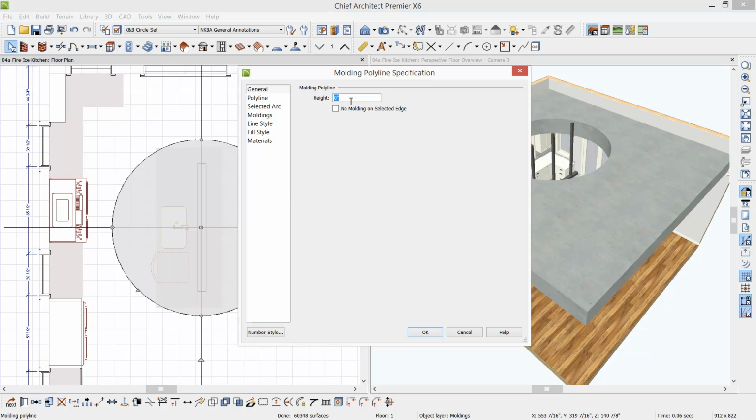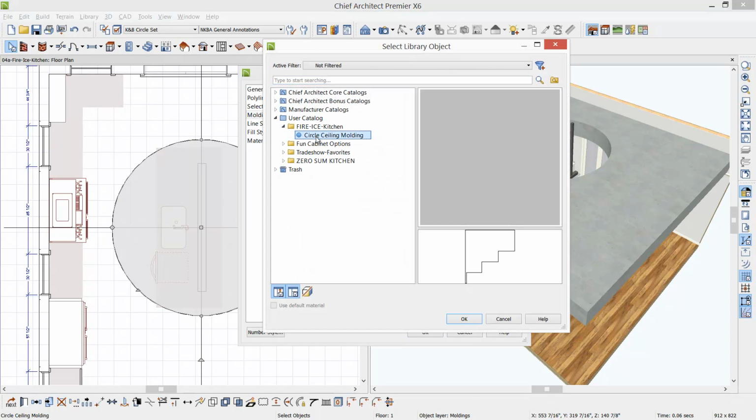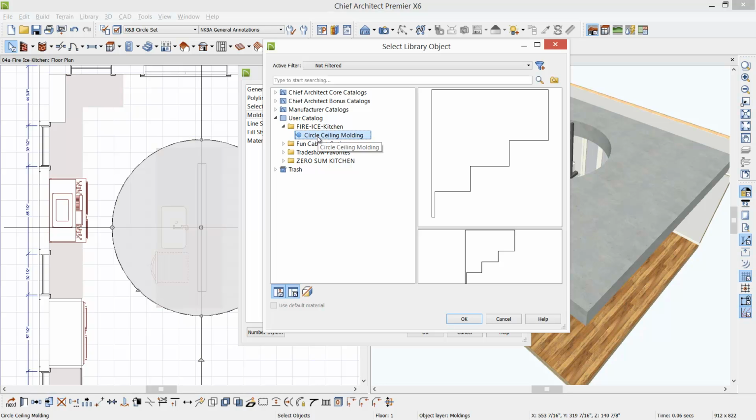And let's go ahead and set the height of that to be 120 inches plus the subfloor of 7/8. And then on the moldings, I've already drawn this molding for the insert. You can see the profile. Now I just went into CAD Detail, drew that profile. These are molding profiles you can draw yourself.